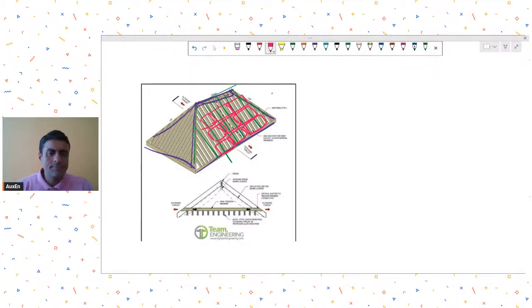And how will the load transfer take place? From this tiling or this roof surface to these rafters, from these rafters partial load on this ridge and partial load on this element, and then this ridge is again supported on these. So finally the load will get transferred to these corners. On corners generally you will have some column or some wall corner to take the maximum axial downward vertical thrust. Also, if you see in this image, and if I were to show you the cross section over here,